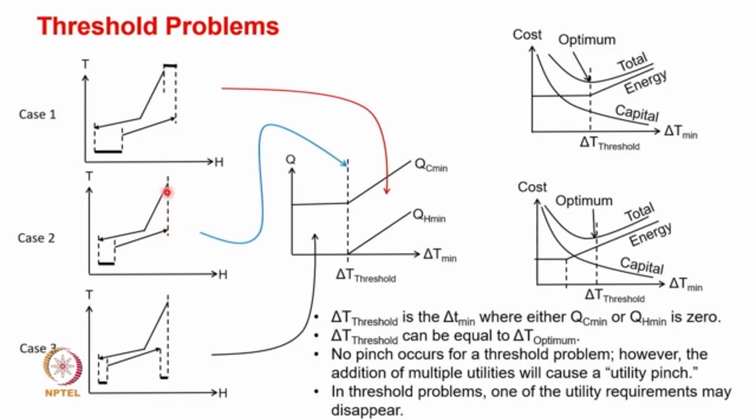The requirement of the hot utility has been adjusted by moving them together. So the coverage is complete at the hot side, but you can see that there is certain void in the cold stream. So anything, and you can further move it back.